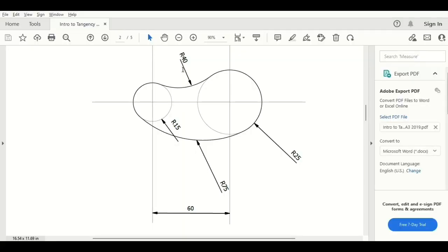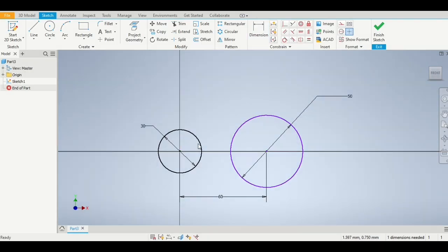And now we will attempt to draw this external arc, which is a radius 40 or diameter 80. But to do so, we need to find the centre point of that arc. So how do we do that? We activate construction lines, then we draw a circle of 110 millimeters in diameter on the centre point of the smaller left-hand circle. So where do we get that size 110?